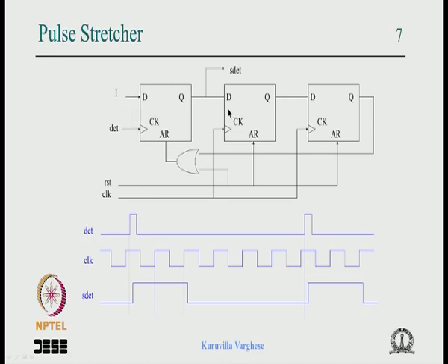What we do is use a 2-stage shift register, because this clock and this pulse are not synchronized, so we are not sure when this will happen, and that is a double clock, so that at least you get one period width here, the synchronized pulse. In the picture it is shown as almost 2 clock periods, but this edge could have been very near, and then you get only 1 clock period, and that is shifted and it is reset.